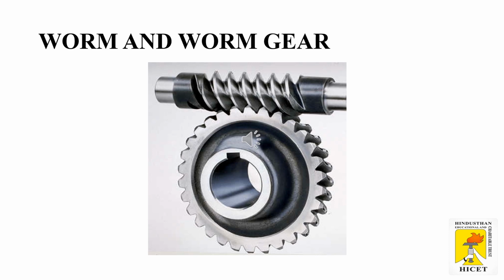Worm gears can be used for high speed reductions up to 400:1. The operation is smooth and quiet. Compared with bevel gears, the efficiency is low and they are very costly. Worm gear drives are widely used as speed reducers in material handling equipment, machine tools, and automobiles.